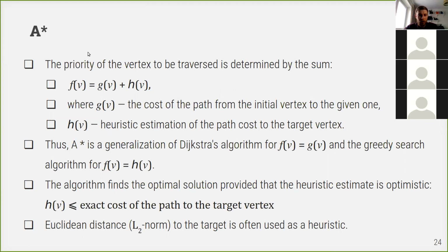We will discuss shortly the basic version of A star, but there are many really smart modifications people came up with to use it for different situations in different environments, and it is widely used in robotics for global path planning mostly. So let's see what it is. As we said, it is informed search, so we have some kind of additional information or heuristic here.